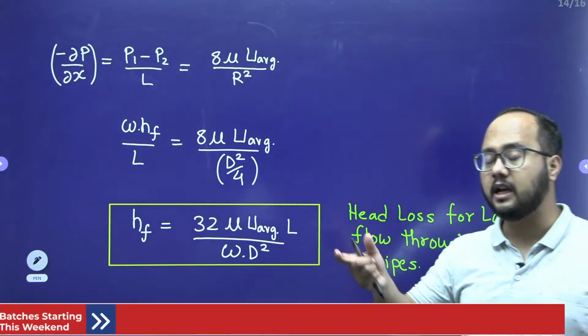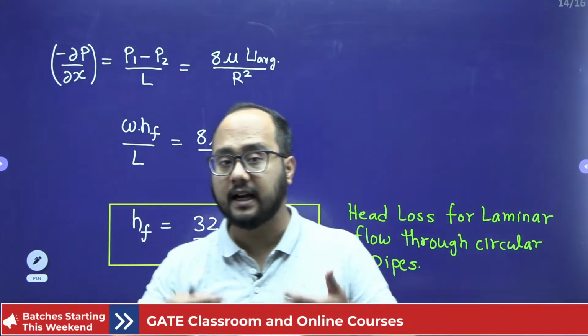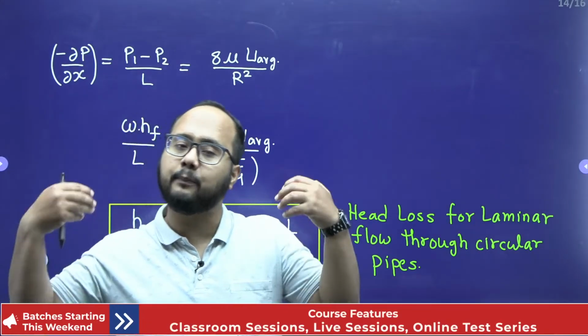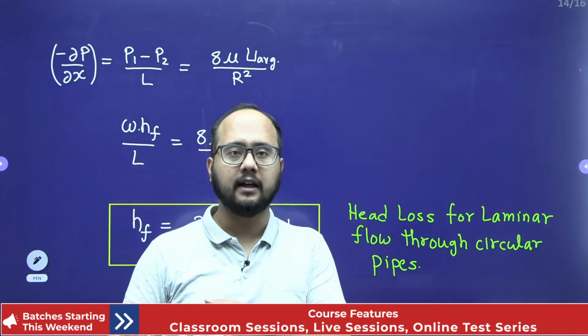Head loss equals drop in piezometric head is valid for uniform flow. But you should also remember the condition, otherwise you will apply that formula everywhere. It should not be like that.